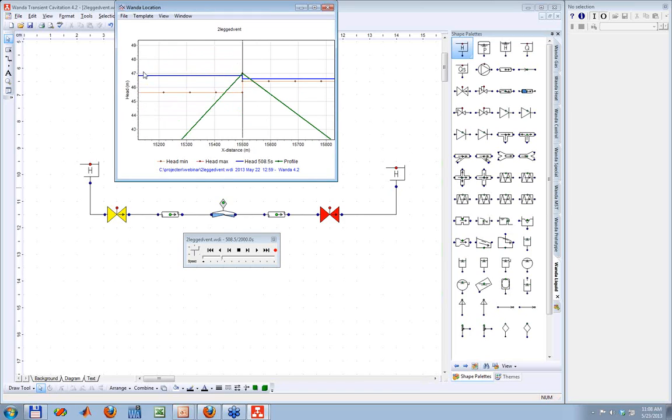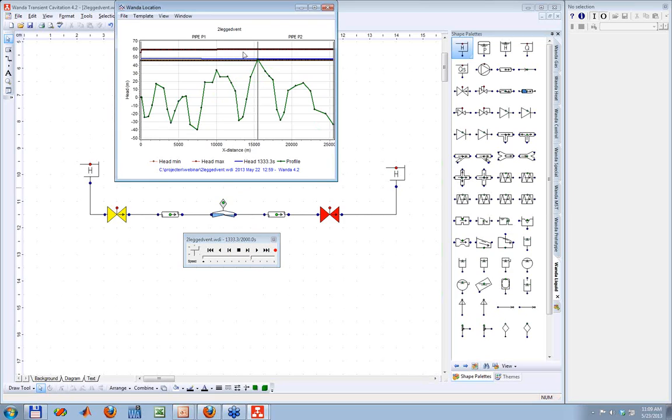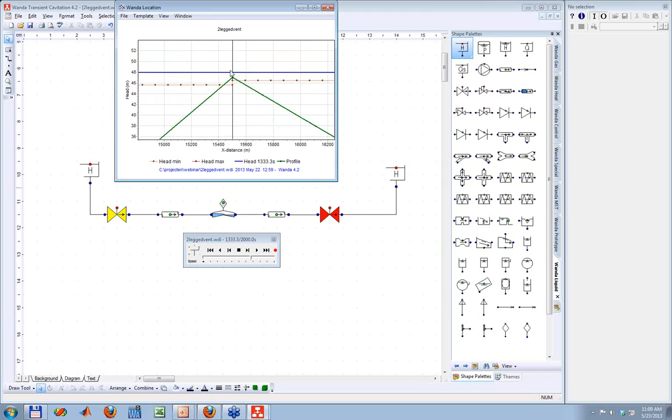you can see that the head on the upstream side is just below the center line of the pipe. So that is the local high point. To that point it's filled. And if I then continue, you can see that the downstream leg is completely filled, and at that moment the last air is being expelled. And at a certain moment, when all air is expelled, I can zoom out a little bit, and zoom in again.